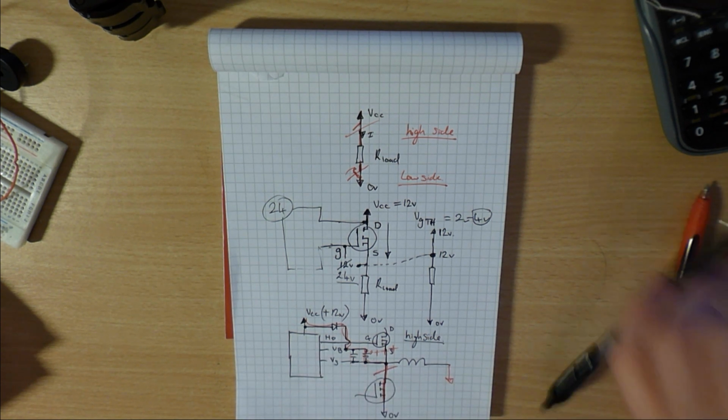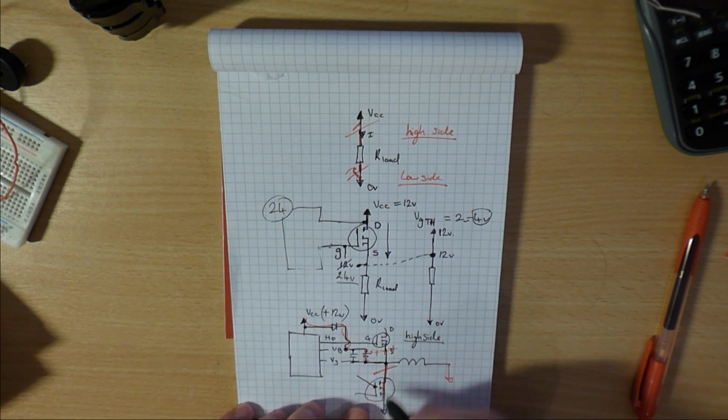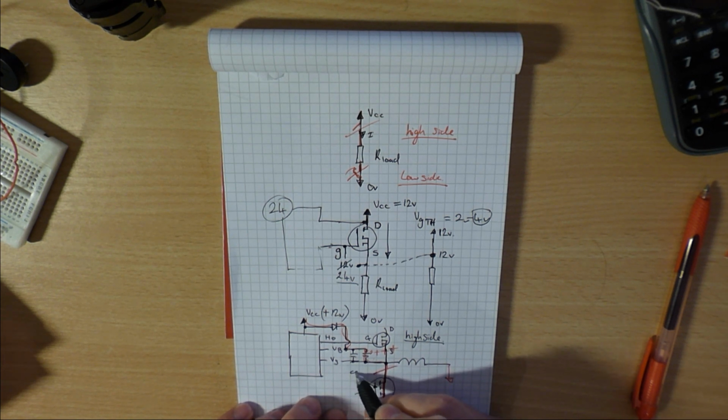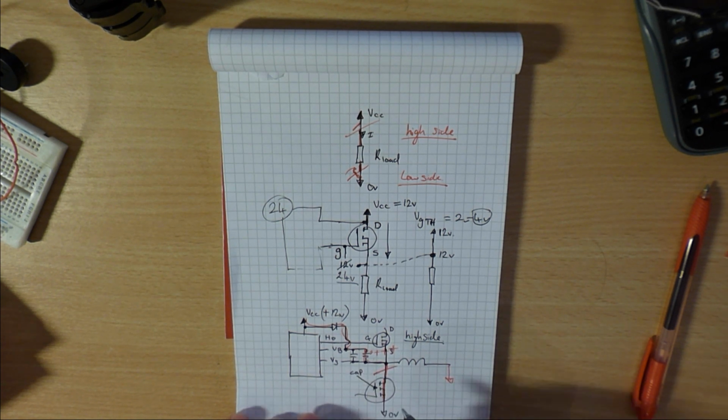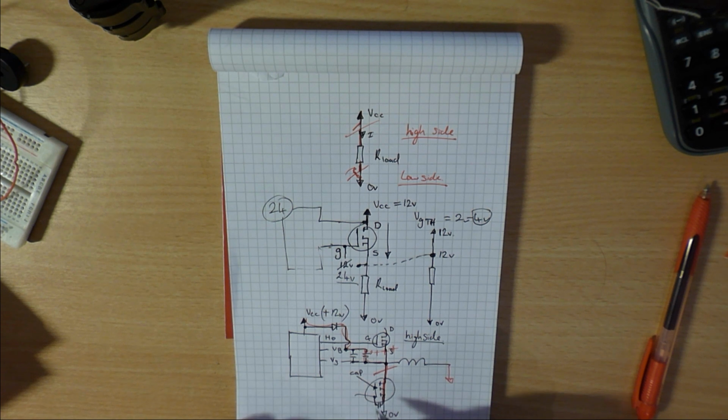Another thing that it does, which is also very important, is here this gate is isolated from your drain and source. Due to the nature of isolation, you get a very small capacitor here, probably in the order of picofarads, I think it is. But if we draw that little cap there, this capacitor, when initially you apply some charge to here, is a short circuit, and you get a very large current flow into this capacitor in order to charge it up.